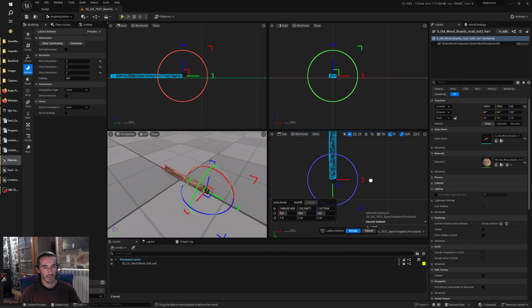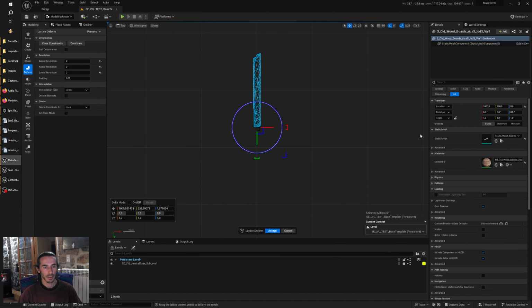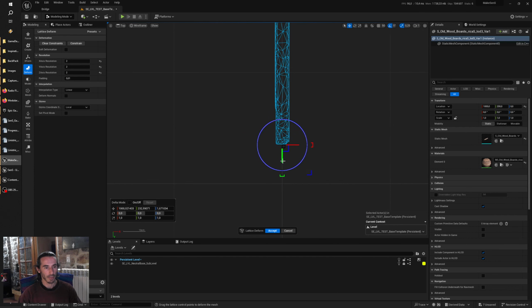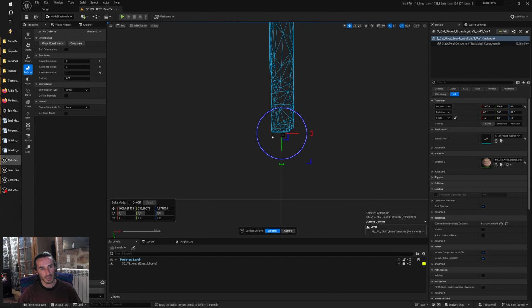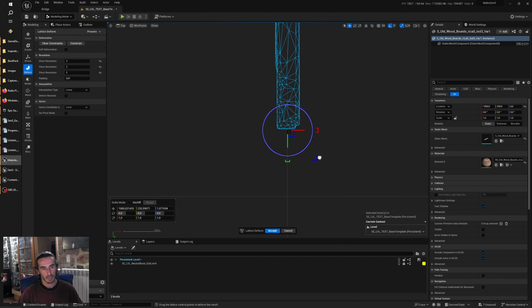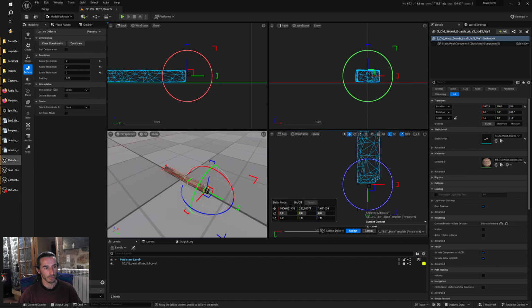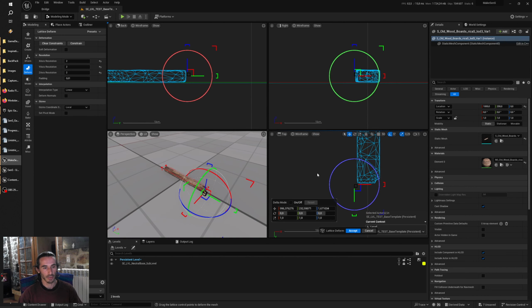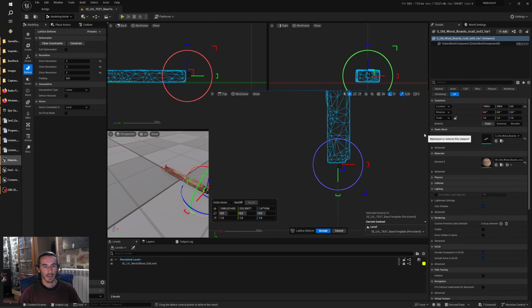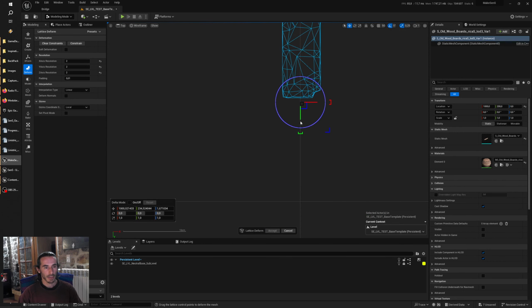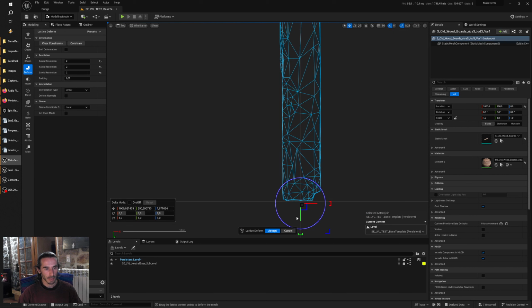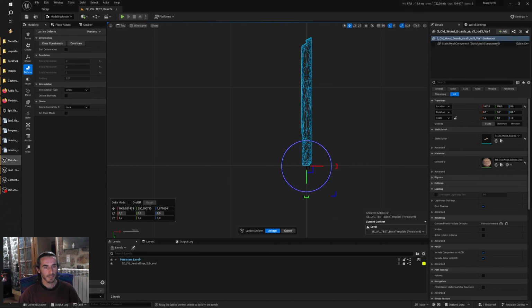So again you can remove the grid to have better control, and you can see that the control points are not visible in the 2D view. It's a bit problematic, so be sure in the 3D view that you have all the points you want and not just some of them. And we can move this in order to be just a little less than 1 meter.